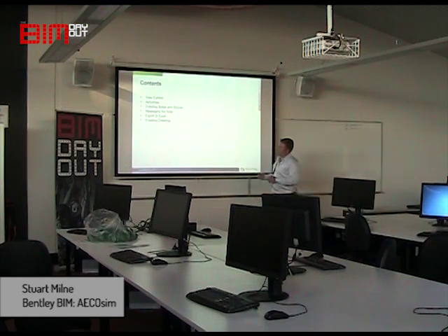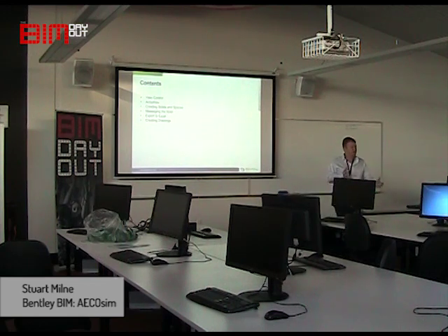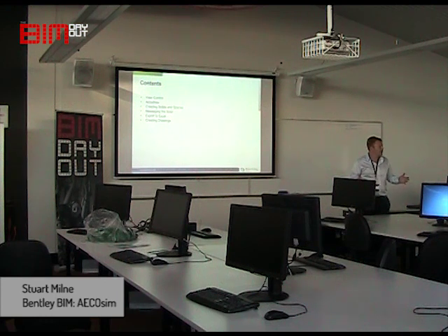Okay? We'll have a look at creating some solids, and what we'll do, we'll actually take a look at a conceptual model or a conceptual solid that might be the envelope of the building. And inside that envelope, we'll put in some spaces which might replicate different floor heights. And we'll tie those two together, and we'll push and pull the solid. Those spaces go with it.